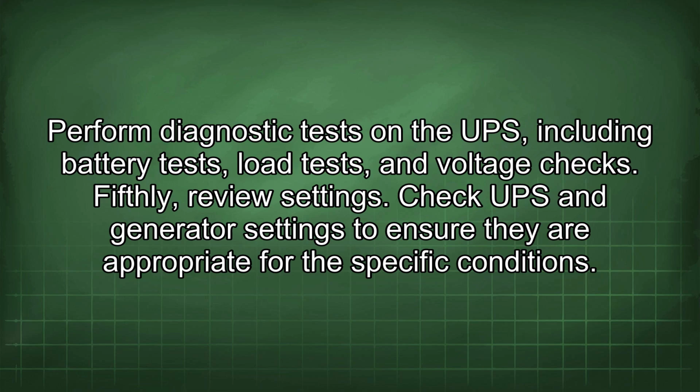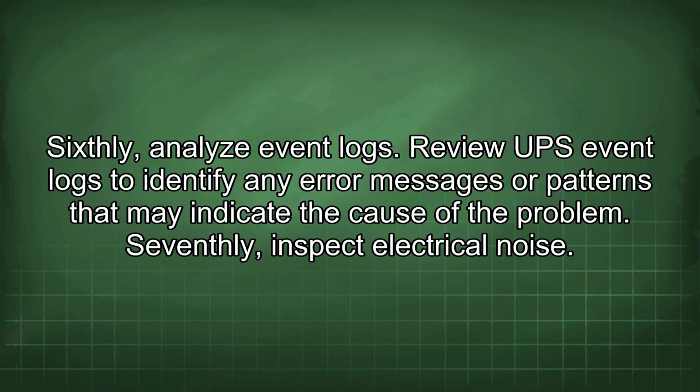Fifthly, review settings. Check UPS and generator settings to ensure they are appropriate for the specific conditions. Sixthly, analyze event logs. Review UPS event logs to identify any error messages or patterns that may indicate the cause of the problem.